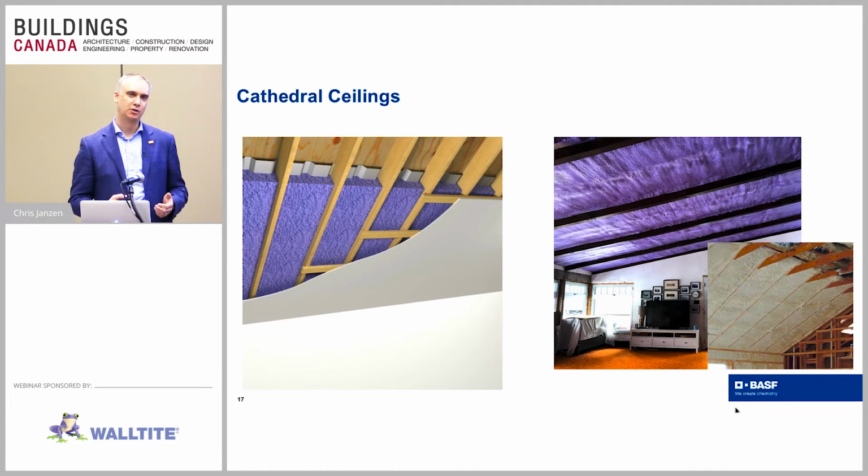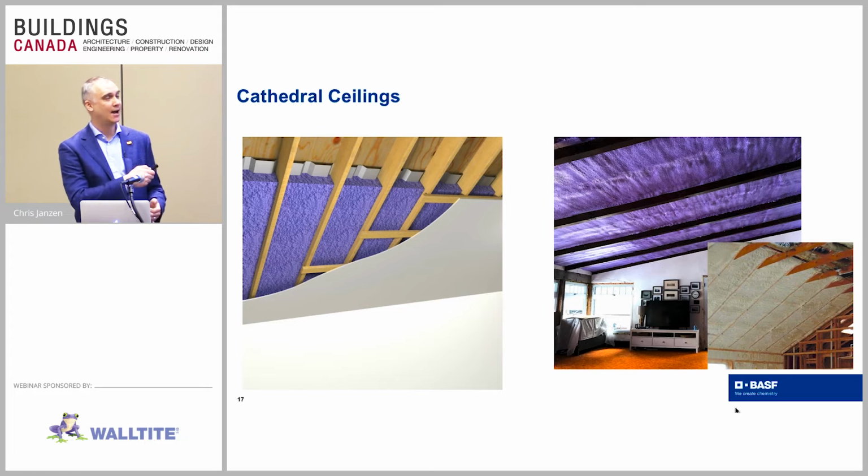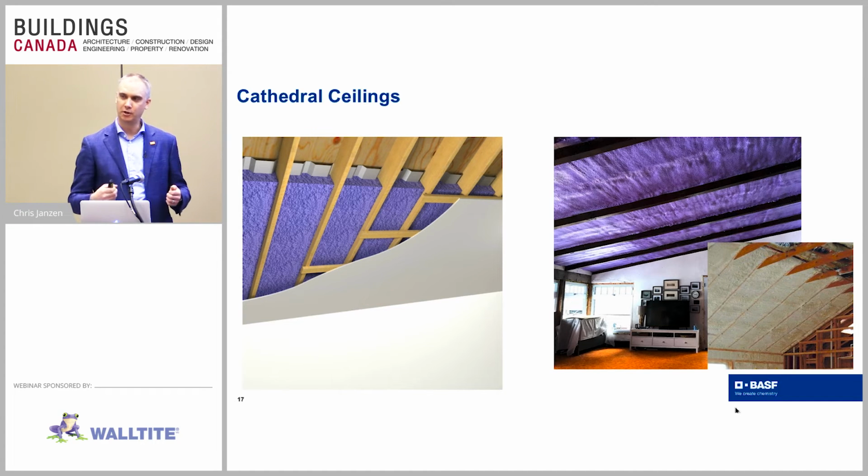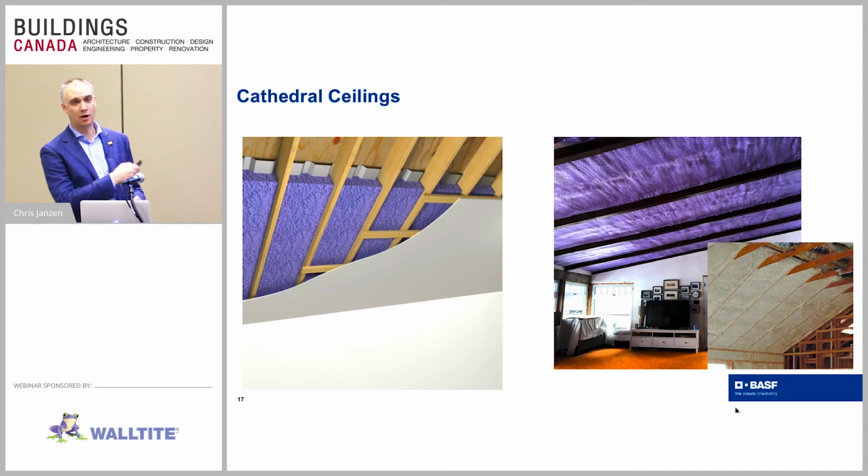So if you're going to use spray foam in an unvented attic situation where you don't have the soffit baffles there, you want to make sure it's on the building drawings and that the building department has already signed off on it. Because if the inspectors come in and see spray foam, when they're expecting to see batt and poly, they're going to say, how do I know that's vented? That's what it shows in this drawing. I don't know what else is going on up there. So get me an engineer in to say everything's fine so I can put that note into the file. By having everything on the drawings, that puts the building inspectors at ease.